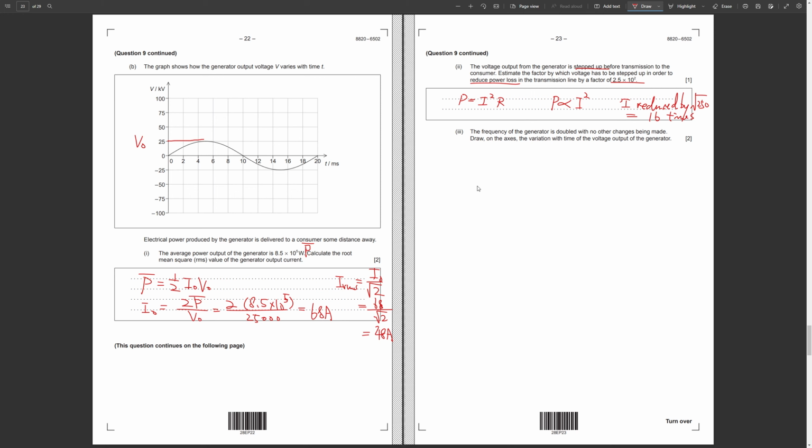And let's take a look at Faraday's law. The induced EMF magnitude is the rate of change of its flux linkage. As the frequency is double, which means the rate here is double as well, the induced EMF should be double. Then the peak induced EMF will be 50 now. This is the new peak induced EMF.